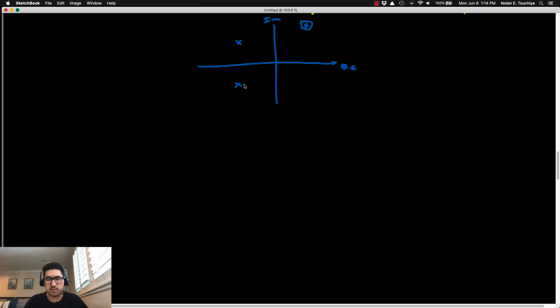We have a transfer function with a pair of complex poles. All the poles are in the left half plane, so this is a stable system, right? If I then have a system that has three poles, so one pair of complex poles and one real pole, but everything's in the left half plane, the system is stable still.